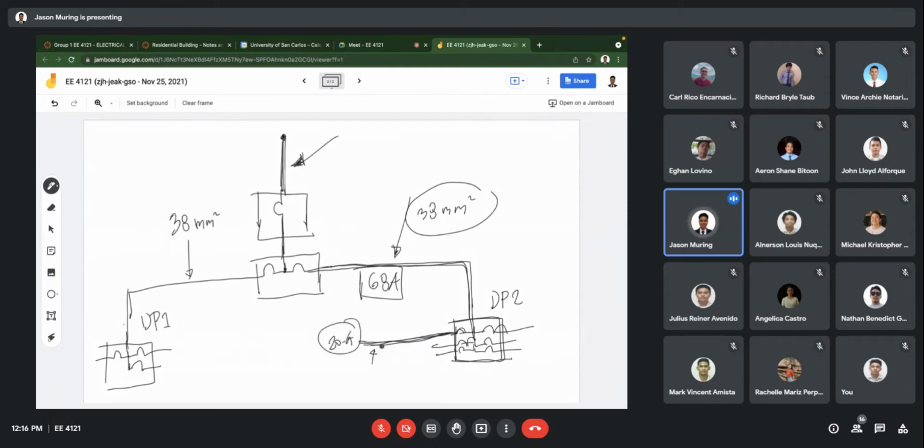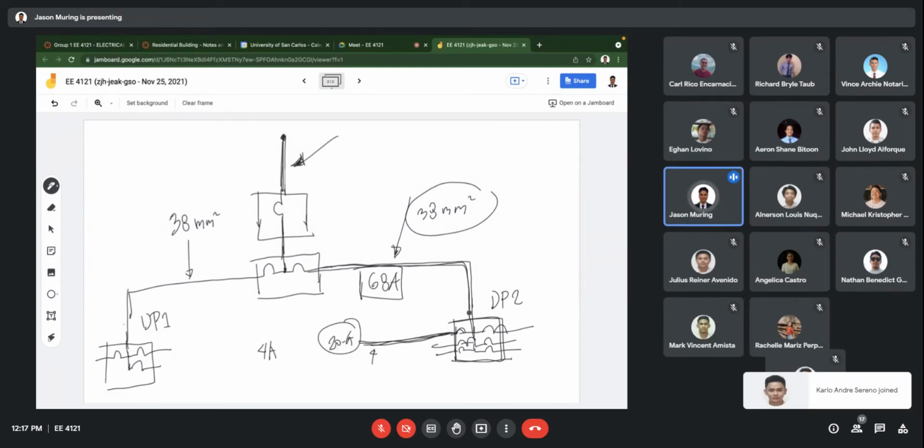Its multiplier is automatically 20 ampere, even if the load here is just a lighting load. So let's say the total connected load is just 4 ampere. If we calculate it based on 4 ampere, surely the voltage drop will be lesser than this rated current calculation. So again, it depends on the state requirement also.